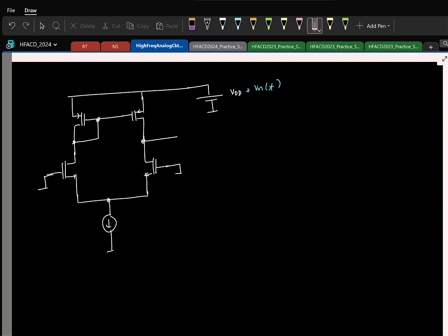Why half circuit can use? Yeah, see, if you recollect, this circuit is asymmetrical, but under what conditions we saw that this becomes symmetrical? If there is a common mode excitation, that is the gate to source voltages for the NMOS and the PMOS are same. Here, what can you say about the VGS of the two transistors? The two NMOS have the same VGS, same with the PMOS. So you can reduce it to a symmetric circuit. That's because these two potentials, they will be same. You can go and short them. So that will reduce a circuit like this.